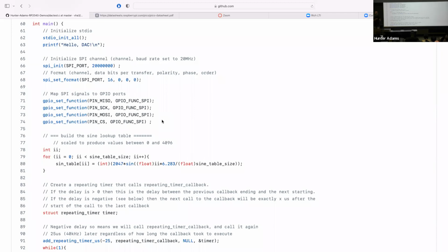You'll notice, incidentally, that one of those broken out wires is red and that there's a piece of electrical tape on that particular one. That's because please don't plug that one into the Pico. There's 5 volts on that, and you can hurt the Pico if you plug 5 volts into it. So I've put some tape on there just to discourage that.